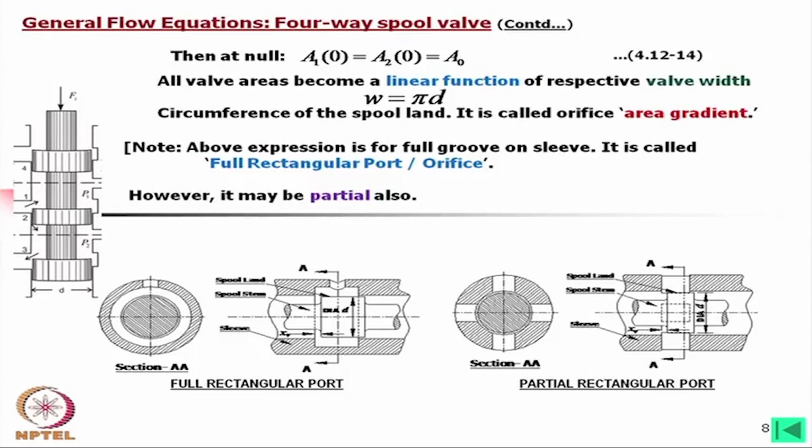You will find that those who are manufacturing these valves, these holes are made. How is it made? Any idea? First of all, you can make a through drill hole and through it you can broach. You know these broaching tools, there will be multiple tools. Say from a circular hole to a rectangular hole.